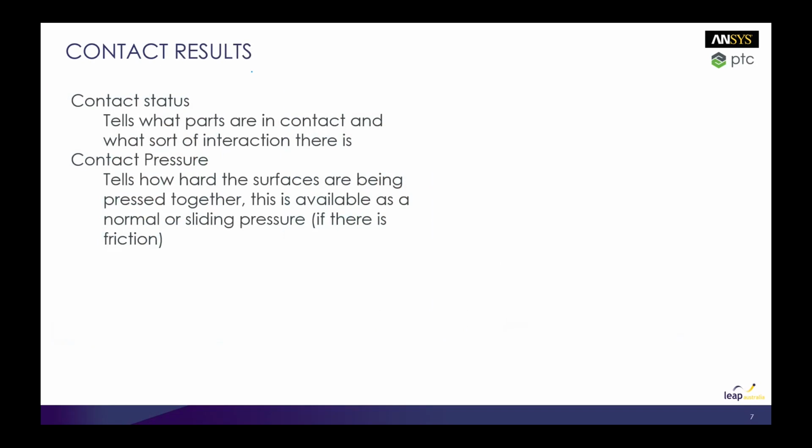Okay, so when we look at contact results, particularly for non-linear contacts, there's a state or status of the contact. It tells you what parts or what area of your part is in contact, and also what the interaction is, whether it's close to being in contact or whether it's far away, and also whether it's sticking or sliding.